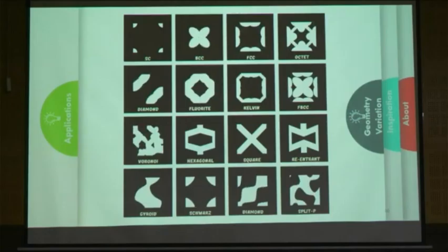And you can see, I told you about the strut formation. We printed the BCC, and the problem is with the multiple formation. Here on the BCC you can see the 4 junction points, the 4 points coming in contact with each other. They specifically told us that for roller-based recoating, if anything happens it will be a problem. Because of the 4 junction points we are getting difficulty. In octet we didn't feel this. You can see there, octet, because octet is a different thing. Because of that only we are getting a problem.